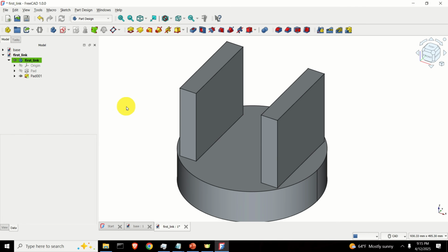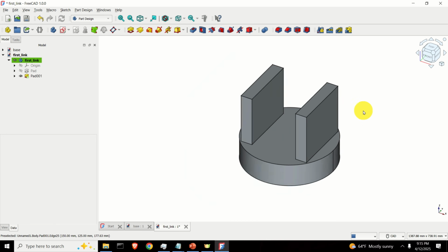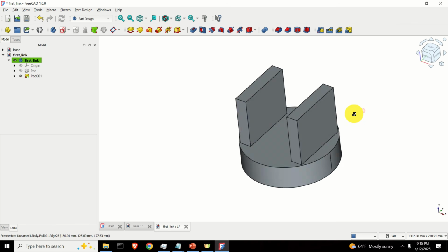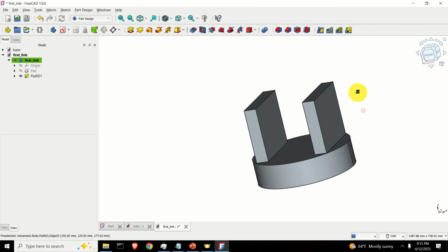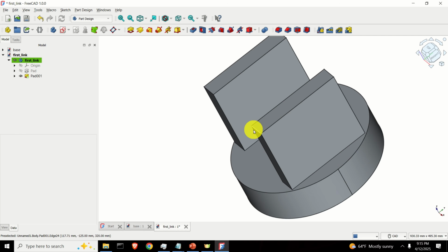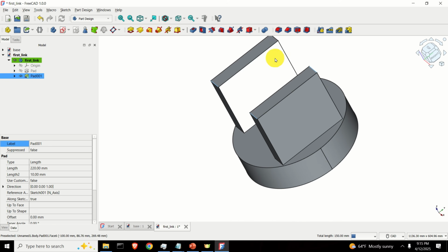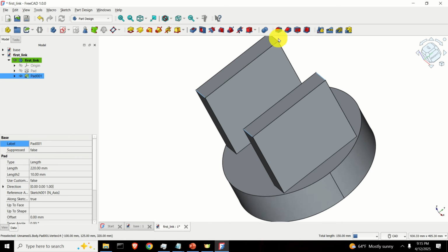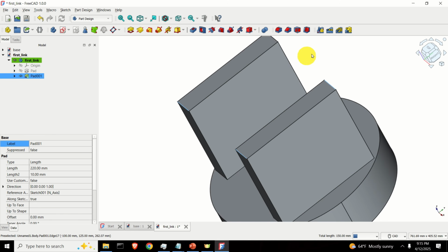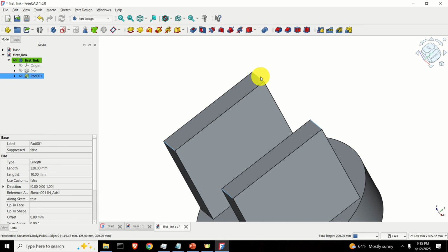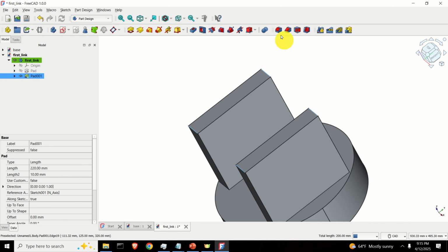So something like this. Good. Okay, here we are. Beautiful. This looks truly amazing. So let's add fillets over here. Click here, then press Control and keep Control and click here, then here, and then let's click on this final edge. So let me now do this and click here, and then you just need to create a fillet.